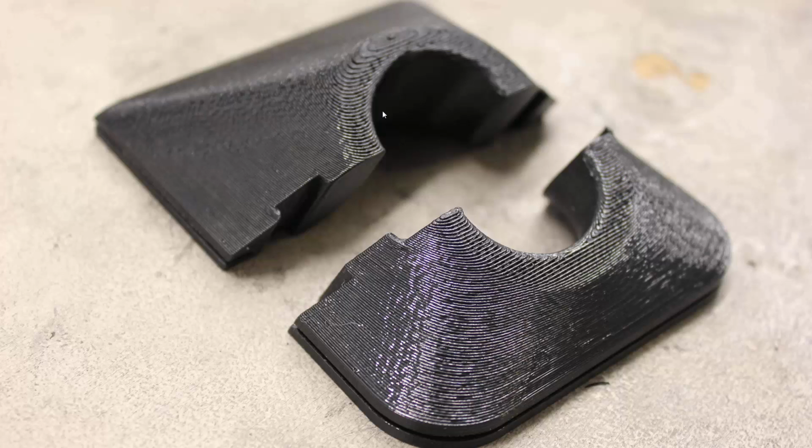I had never done solvent smoothing. A lot of people call it vapor polishing, vapor smoothing. Normally how that works is you would heat up a solvent, say acetone, and allow the vapor to kind of consume the printed part, and it smooths it out. Well, I didn't have a good way to heat up the solvent, which ended up being nail polish remover, which is just acetone. And I didn't have a way to contain it.